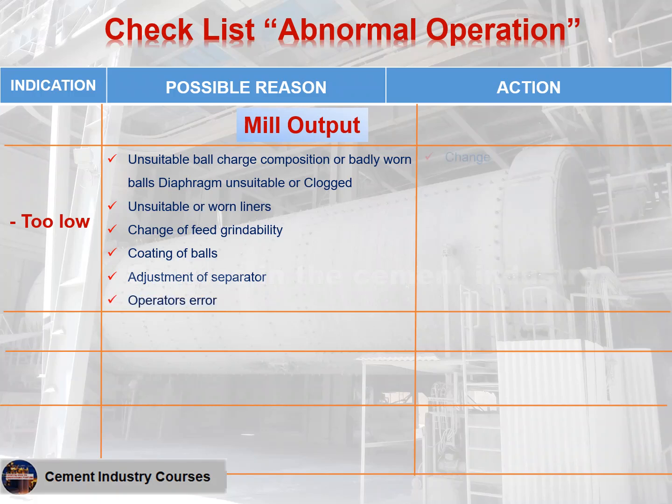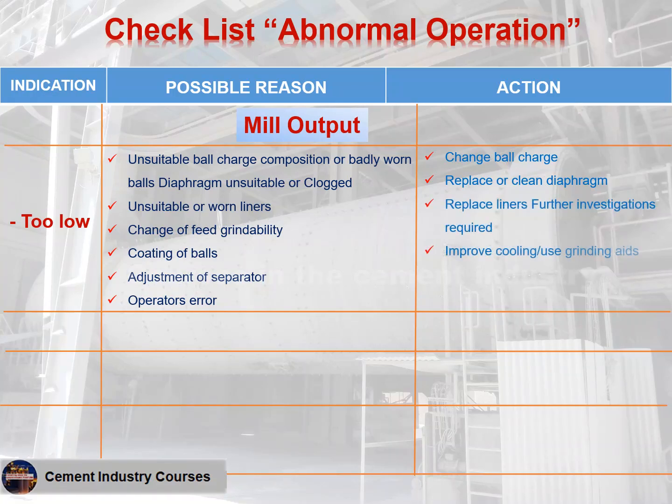Action: change ball charge. Replace or clean diaphragm. Replace liners. Further investigations required. Improve cooling or use grinding aids. Adjustment. Instruction or training.